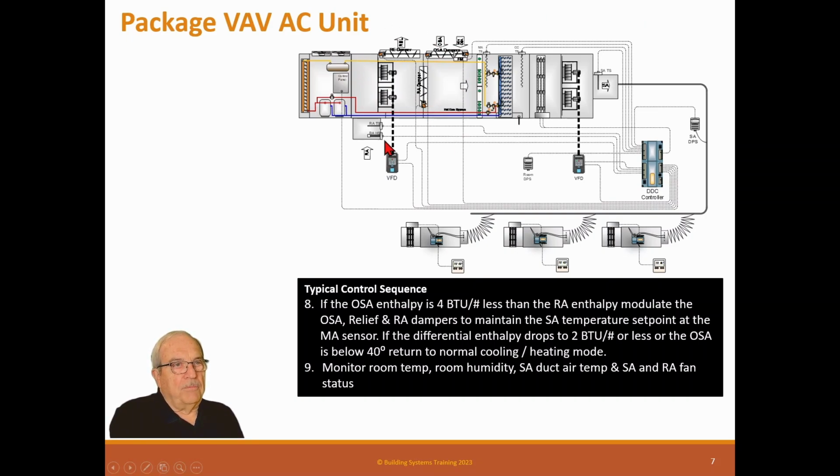Now, remember that with a humidity sensor and a temperature sensor, we can calculate the enthalpy. What we're trying to do is make sure that the enthalpy of the outside air has enough space, enough energy, that we can actually use it to cool the building. And that works really well.